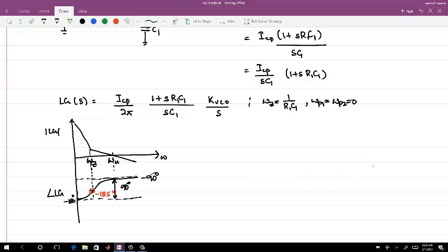We started with the type 1 PLL, if you remember, and the frequency acquisition range of the type 1 PLL is limited. So we needed one additional integrator in the loop. That time also we were having the VCO. In the case of a VCO, it converts the control voltage to frequency proportionally, but the output phase is an integration of this frequency. So that integration is a frequency to phase conversion.